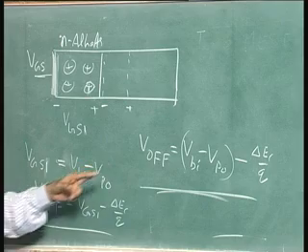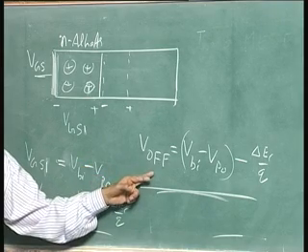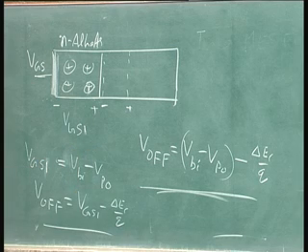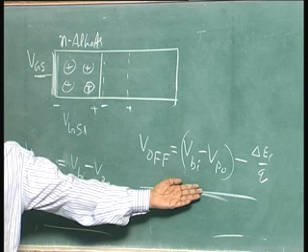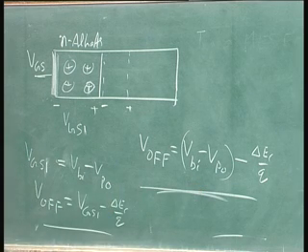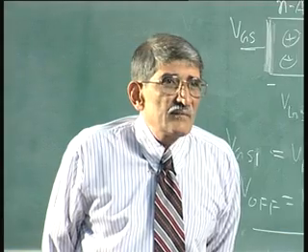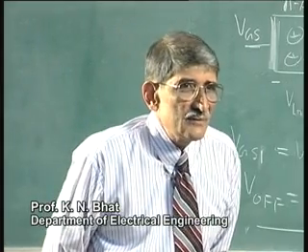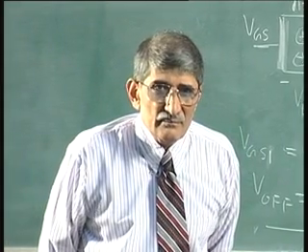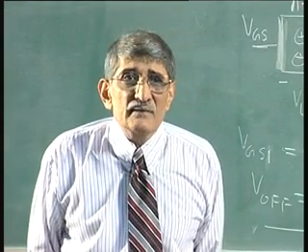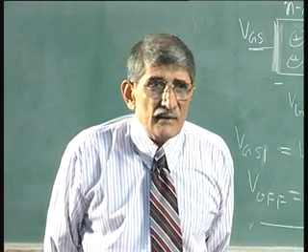Now, if I increase the gate voltage with respect to the substrate positively, let us give some numbers. VBI minus VP0, let us say, is equal to 0. Okay. VBI minus VP0 is 0, it is possible. Pinch off voltage equal to 0.8 volts, VBI is 0.8 volts, that is 0, just to give an idea. And delta Ec is 0.3 electron volts. What is the off voltage?